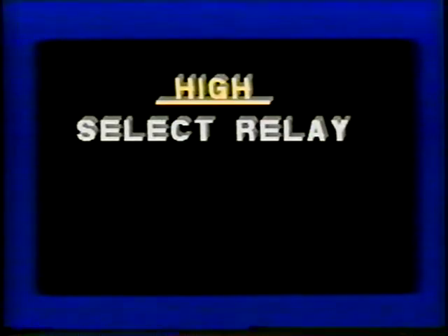The high select relay is used where the system requires the comparison, selection, and transmission of the higher of two proportional input signals. This application drawing illustrates the highest of the two inputs being transmitted as the branch output.